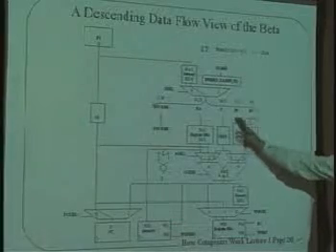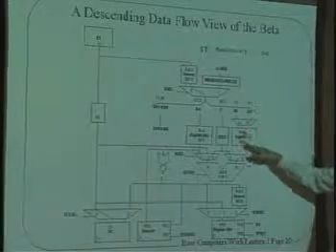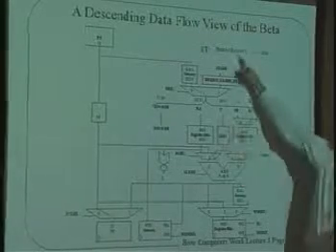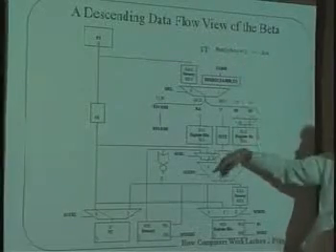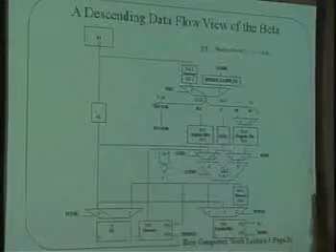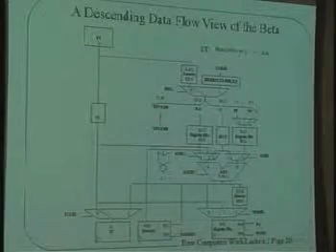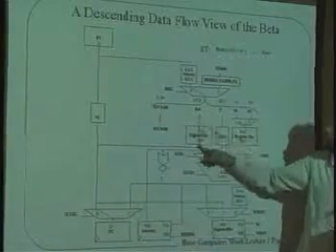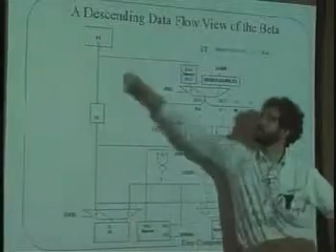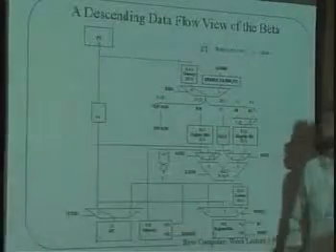So RC is going to get chosen here. It's going to get looked up, going to get fed into here, and will be added to C, just like it says right up here. And that sum will be used as a pointer into the big slow memory over here, and that will be the location that we write the data, which is the contents of RA that comes out here. Nothing has changed over here with bumping the PC by 1 to get to the next opcode.